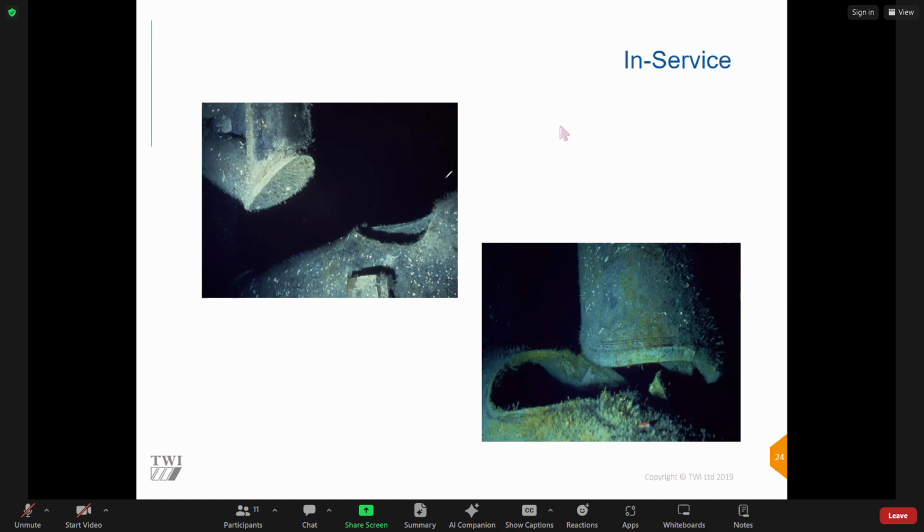So visual inspection, then MPI, ACFM to establish whether or not we've got a crack-like defect. Okay, well, like I said, obviously it's gone unnoticed. It's got to the point where it's then failed, because the rest of the material will no longer withstand the load.